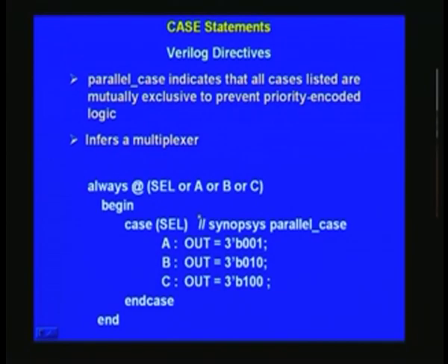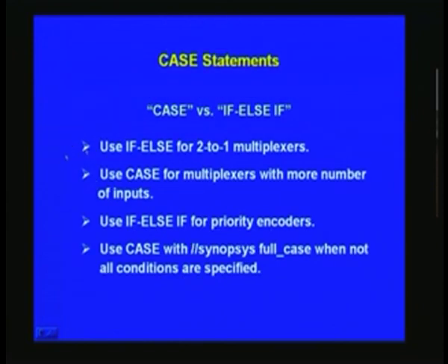Maybe Xilinx may not support one of these, I am not sure, you will have to experiment with it and find out. But it is most likely that it will work on the Synopsys platform, which is basically a tool for ASIC design. So as far as possible, try to avoid full case and parallel case. In fact you can write code, although it may be a little longer, but it will be safer code if you go the usual way.